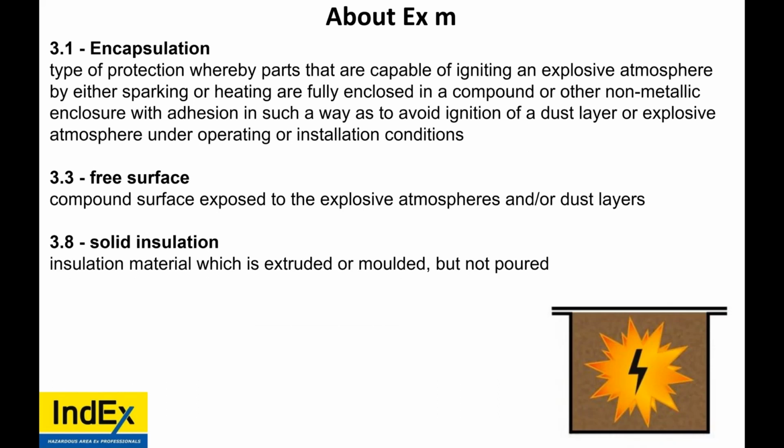So encapsulation is a type of protection whereby any parts that are capable of igniting an explosive atmosphere by either sparking or heating are fully enclosed in a compound or non-metallic enclosure with adhesion in such a way to avoid ignition of dust or gas atmospheres under operating or installation conditions and also certain fault conditions. So solid insulation means that insulation material which is extruded or molded but not poured. So solid insulation does not refer to the EXM compound. Okay?